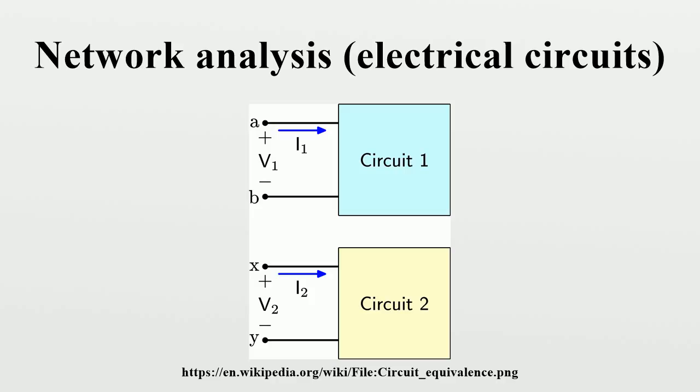Two-terminal component transfer functions. For two-terminal components, the transfer function, or more generally for nonlinear elements, the constitutive equation, is the relationship between the current input to the device and the resulting voltage across it. The transfer function, Z, will thus have units of impedance, ohms.